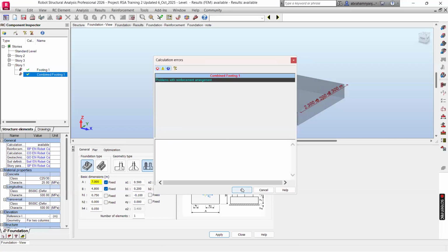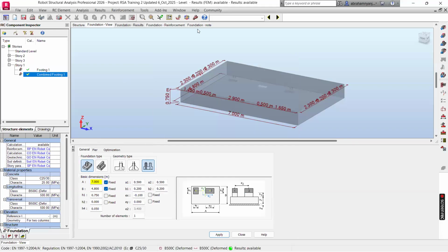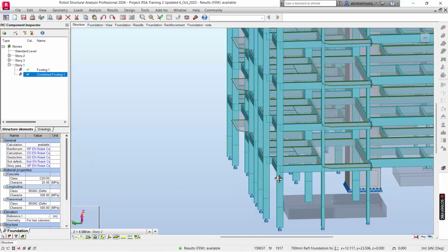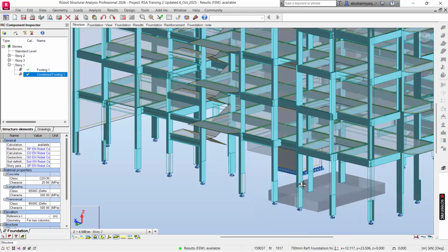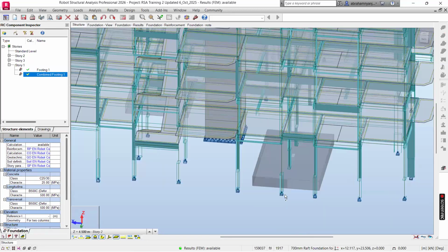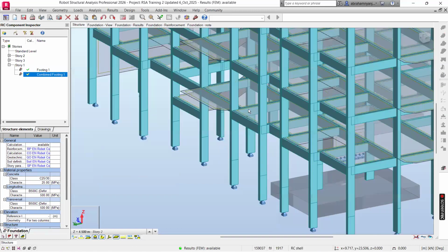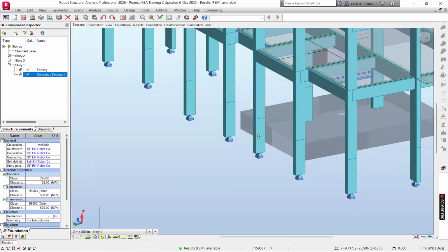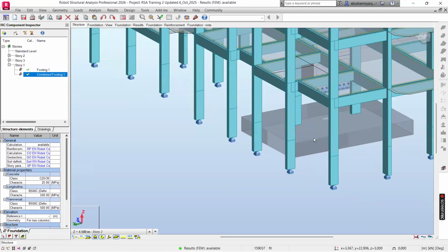As you can see, this one is okay, but now let us go back to the structure and we see what we have adjusted. How is it interacting? I think the 7 is too big. Okay, to have a better understanding, we can first design one footing, these ones, because they are isolated, they're one by one, and we see their interaction with this, then we can adjust this to meet what we want.